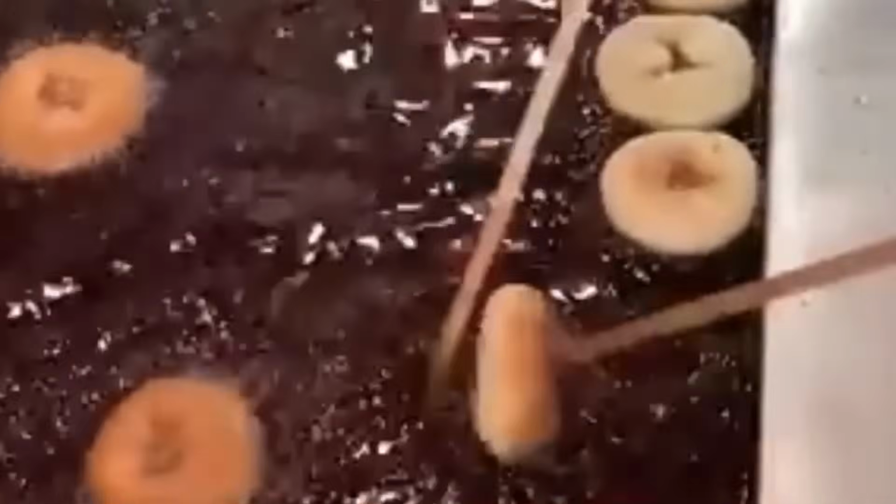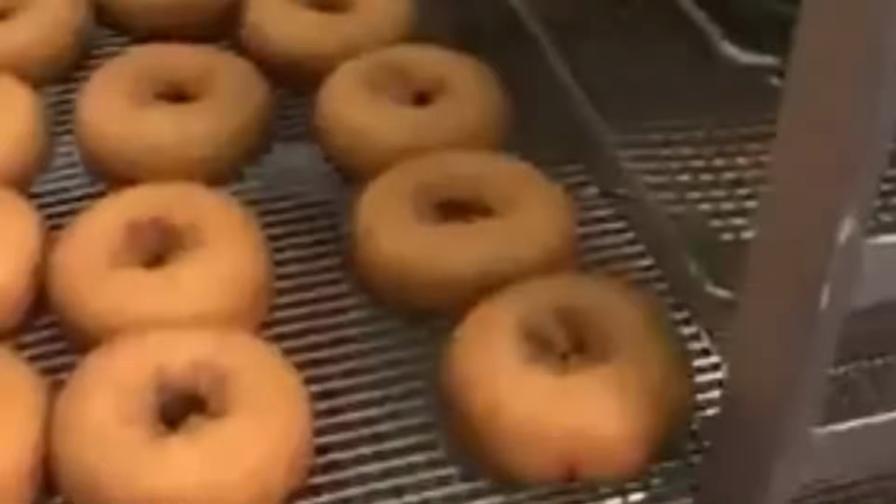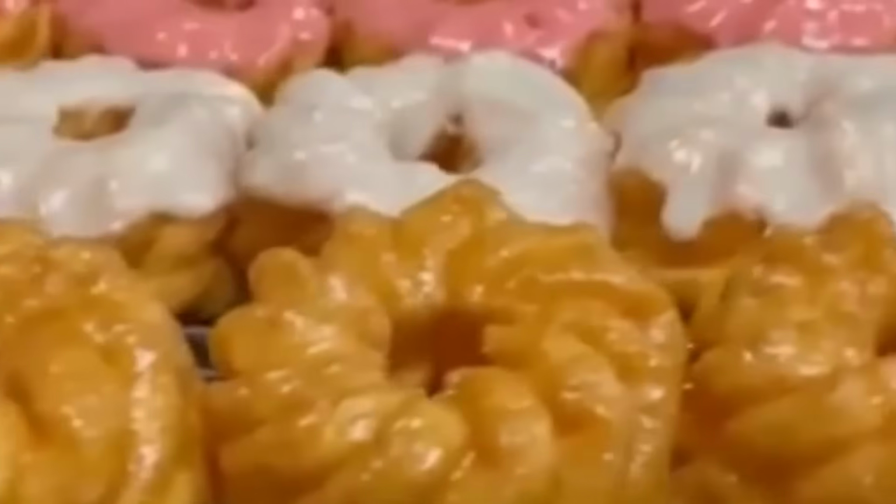Flour is dispensed first into the bowl, followed by sugar and salt through calibrated rotary valves. Shortening is pre-melted in a jacketed vessel and dosed into the bowl using a metered pump. Liquid eggs are held in chilled tanks and dispensed through a pneumatic valve. Yeast is hydrated in a separate tank before being introduced into the mix stream.